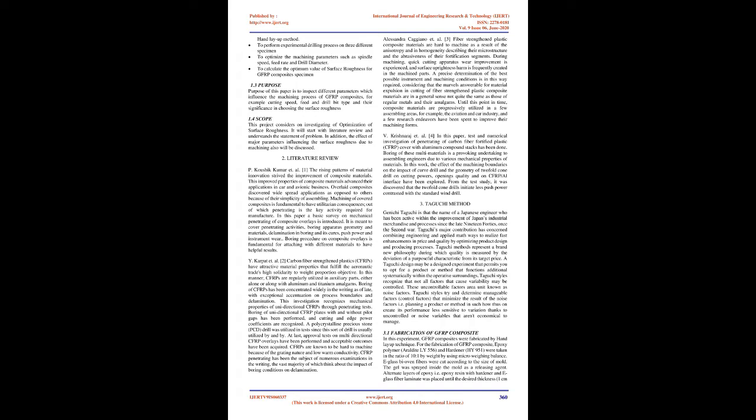1.2 Objective. To manufacture glass fiber reinforced plastics specimen with varying concentration of epoxy resin using hand layup method. To perform experimental drilling process on 3 different specimen. To optimize the machining parameters such as spindle speed, feed rate, and drill diameter. To calculate the optimum value of surface roughness for GFRP composites specimen. 1.3 Purpose.